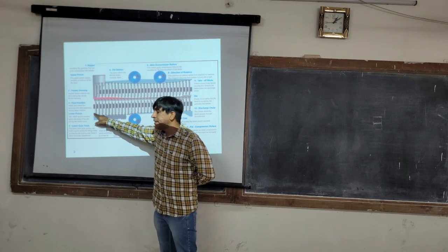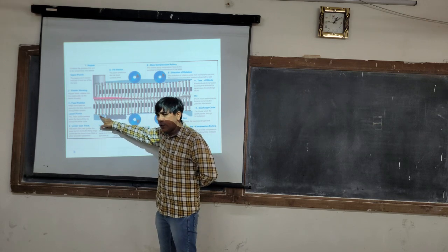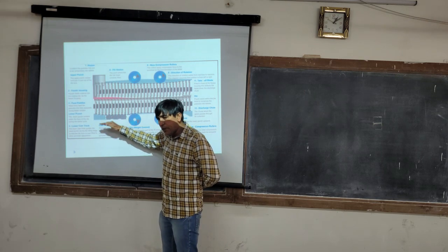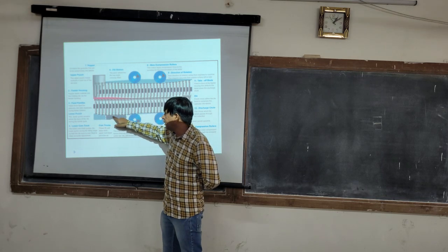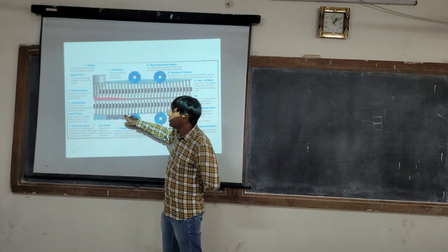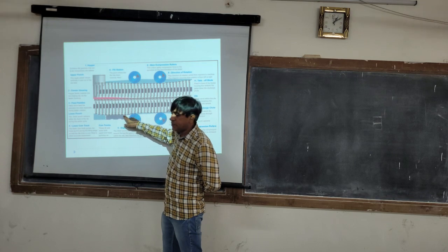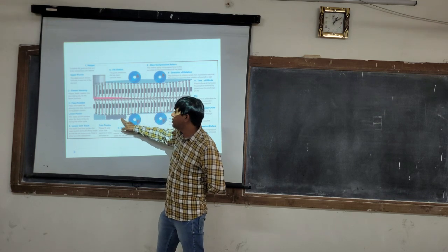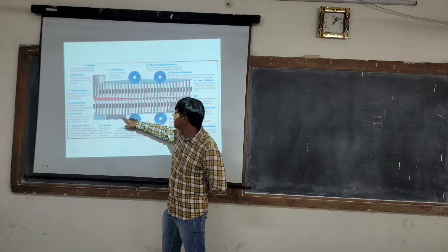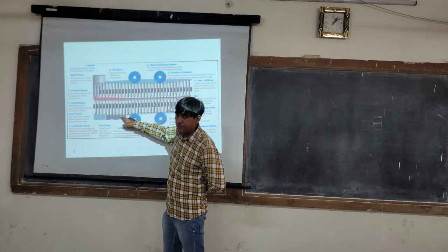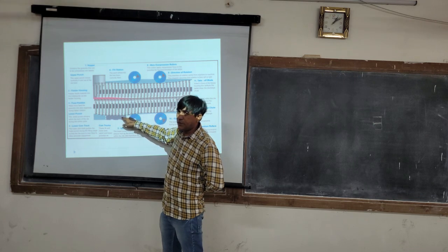As you look at this, there is a ramp. So the lower punch is lowering, it is coming down and it is increasing the fill volume. Over here, till this point, the filling will take place. Now, there is a weight adjustment knob over here. We can increase the elevation over here, and that helps in the weight adjustment.